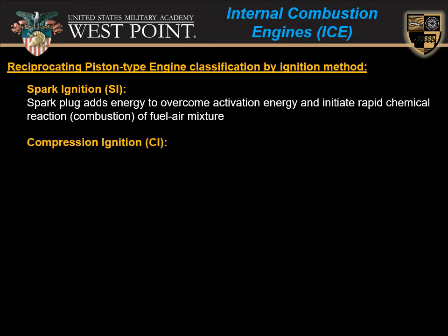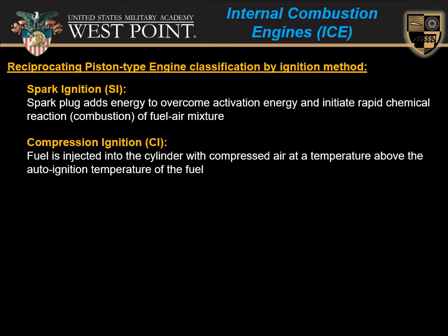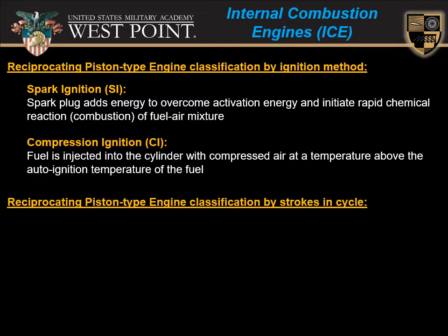Conversely, if you have a compression ignition engine, the fuel is injected directly into the cylinder with compressed air. Now that compressed air, due to the compression, think ideal gas law, is at a high enough temperature that when the fuel is injected, it immediately vaporizes and ignites because the temperature is higher than the auto ignition temperature of that fuel.